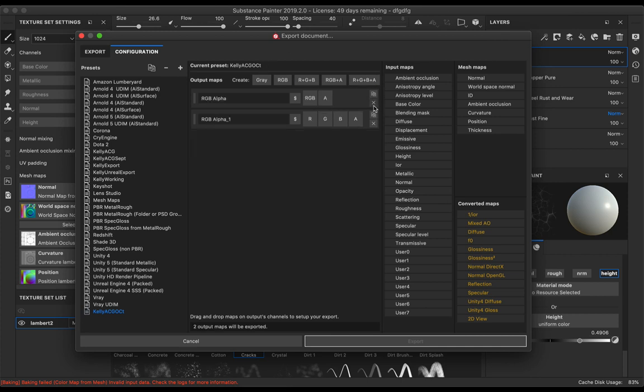I need a base color and I need a normal map. My base color is RGB. In here, there's one base color. You don't have to worry about having to figure out which one to bring. There's only one. Click and drag it. I want this to be RGB. This is going to take every single base color from all of your materials, and it's going to hook it up here. Naming conventions, T underscore.